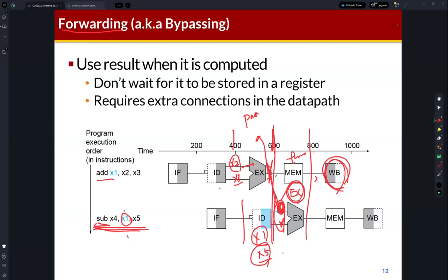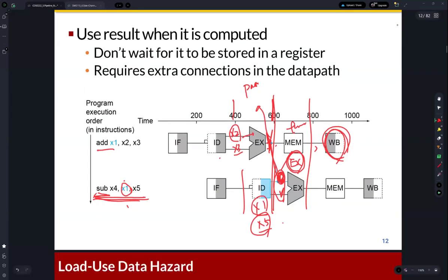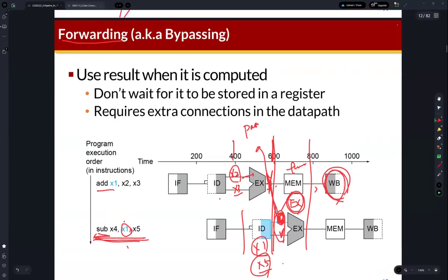So in the hardware implementation, the hardware implementation can be different from the software model. Okay, it's because when I explained the software model, I explained that the software just assumes that instructions are executed atomically. Atomically means that this instruction is executed and completed, and then the next instruction is executed and completed. So actually this is the single cycle processor model.